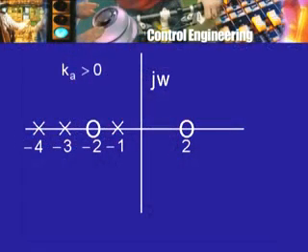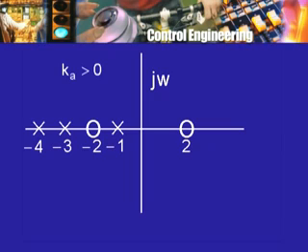So to find out whether a point on the imaginary axis, which looks like this, j omega, is on the root locus, we will have to find out the angle subtended by this point at the various zeros and at the various poles, and then write down that expression: sigma angle subtended at the zeros minus sigma angle subtended at the poles equal to pi plus or minus 2k pi. Now if I choose a particular value for omega, for example let us say j2 instead of any arbitrary unknown omega, then it is not very difficult to find out if the angle condition holds.